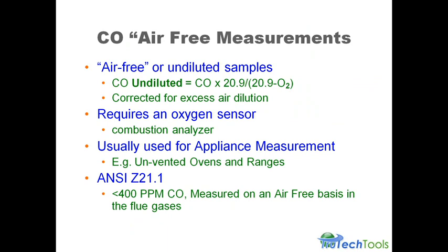In order to get undiluted CO readings, you have to use a combustion analyzer. You cannot use a raw CO sensor, and they sell them. They sell analyzers for $800 or $600 that measure CO, and they aren't a combustion analyzer, but all they make is a raw CO measurement. And that raw CO measurement is no good for meeting any of the standards.